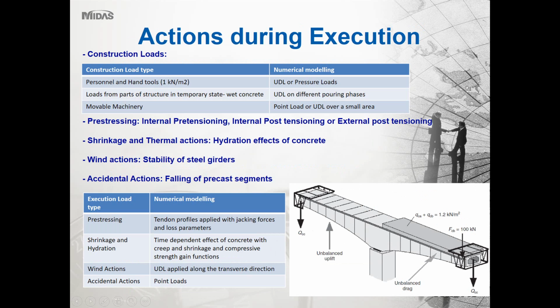Okay, now let's move quickly to the actions during execution. During construction, we may have a totally different scenario, but we need to design the structure under construction separately from the one covered under service. So during construction, we may come across simple UDL or pressure loads, like people moving around on the deck, movable machinery, etc., which can be put in as a point load or UDL over a small area.